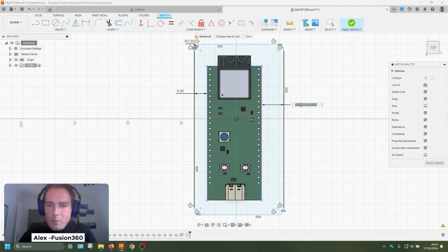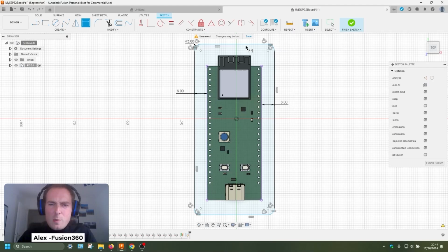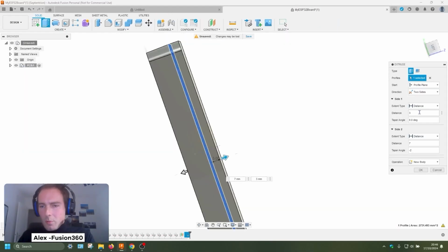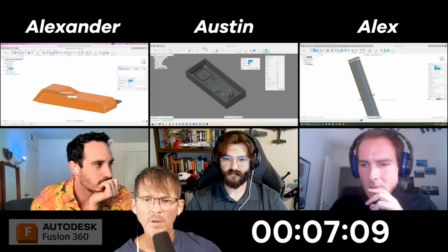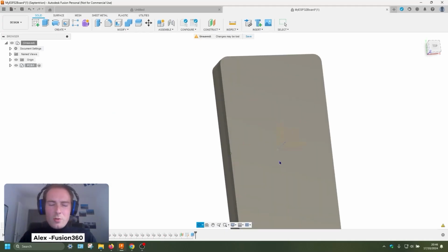So right now I'm working on making the first outside perimeter. Fusion's pretty laggy for some reason when I have this sharing on, but it's not critical. I'm going to go with a nice little 2-degree taper that generally works for all injection machines. Is this for the draft, you mean? A draft, yeah, draft.